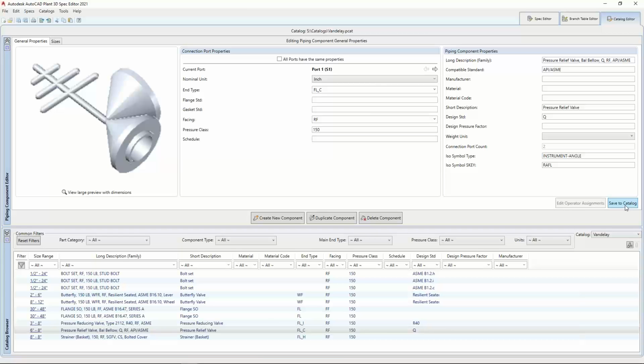So pretty much that's all I needed to do to get EndCodes set up, which one it's going to use. Just set the end type in the component itself, and then that points it towards the piping connection, and then that points it towards the bolt standard. A little jumping from one to the other.